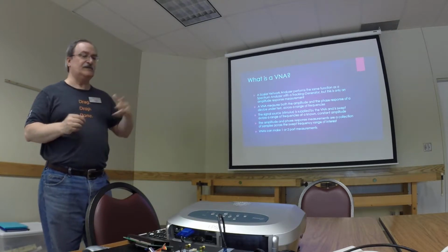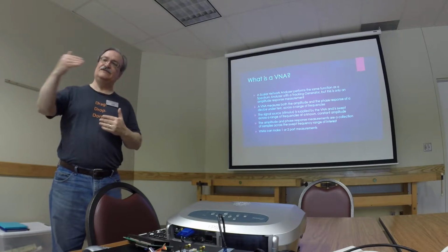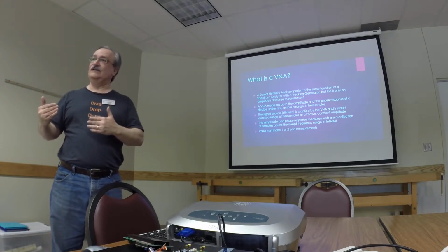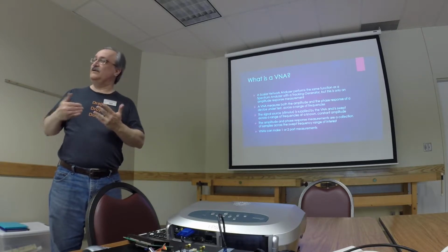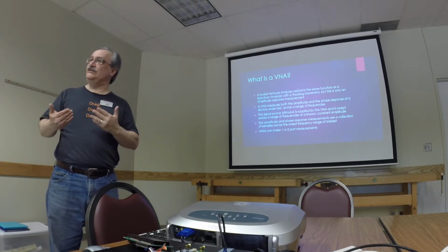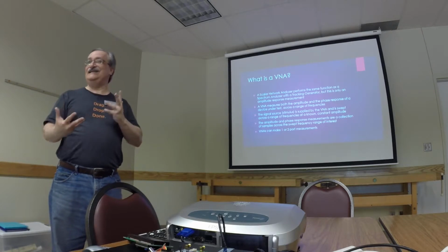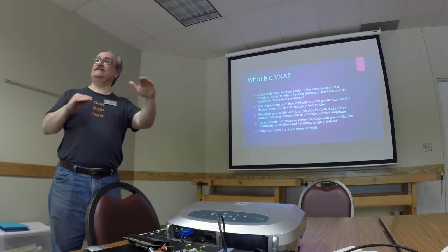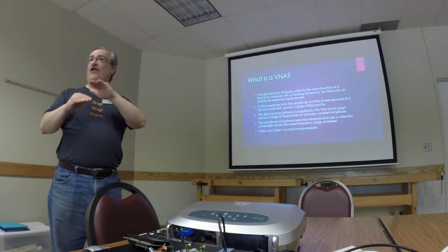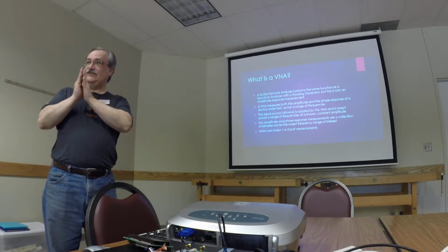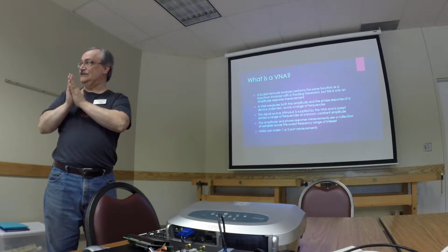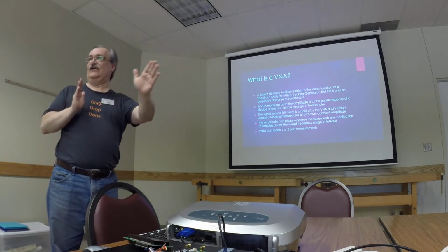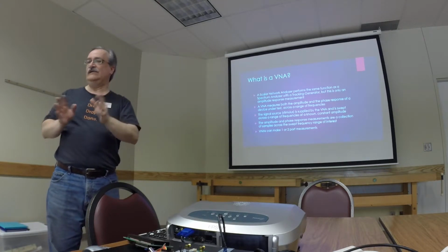Now, as I mentioned, the amplitude and the phase response is a series of samples. So you have a phase detector as well as a magnitude detector. What really makes it special is the phase detector, because as it turns out, long story short, that's not the easiest thing to build in a way that's linear across the set of frequencies. They're not hard to build if you're just interested in a very narrow range of frequencies. You can get phase, but across the broad spectrum of frequencies, that's a little harder.